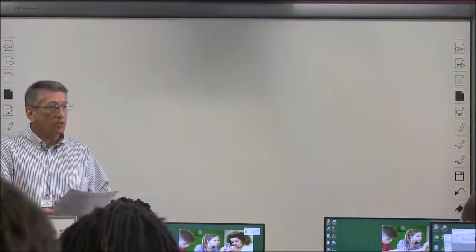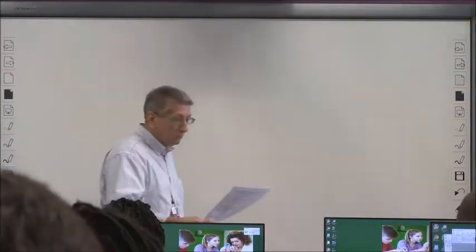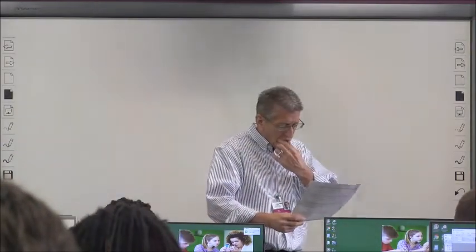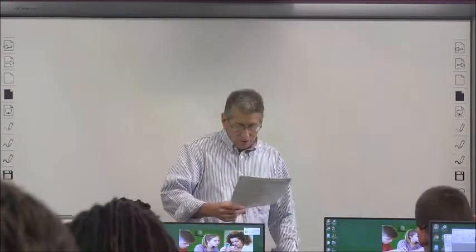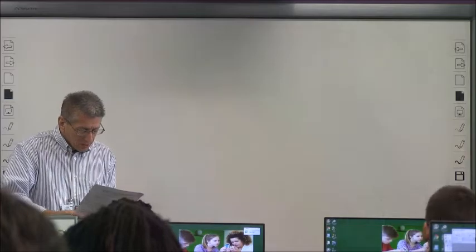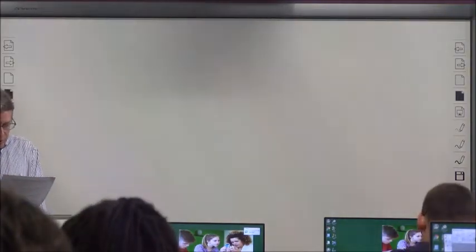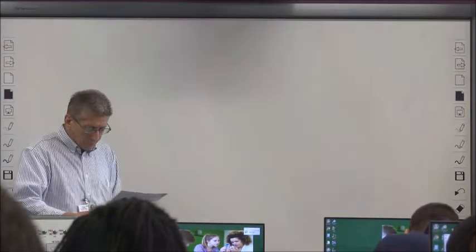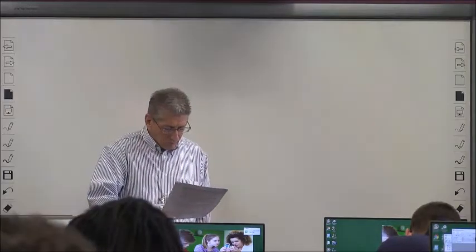Where are we at? Number 7, okay. What value will be in the input image table? 1. Yes, good. Aaron, what do you remember? If a normally open proximity switch is programmed into your PLC logic as an XIO instruction, and then the proximity switch is made, what will be the state of the instruction in the logic? 0. How did you figure that out?